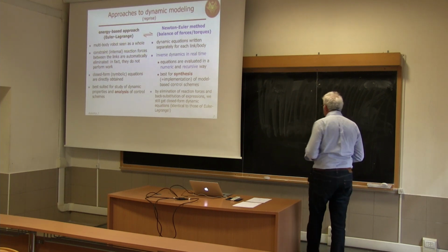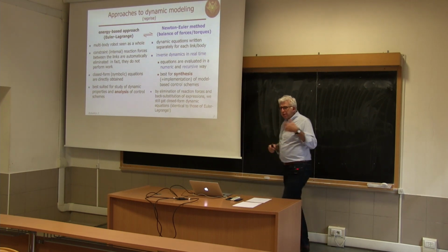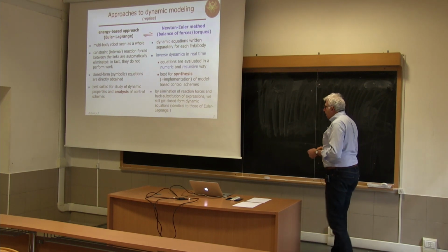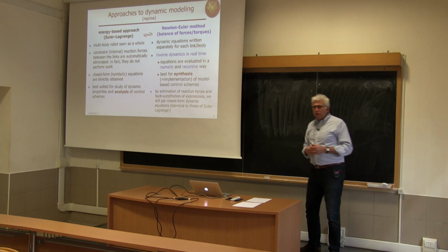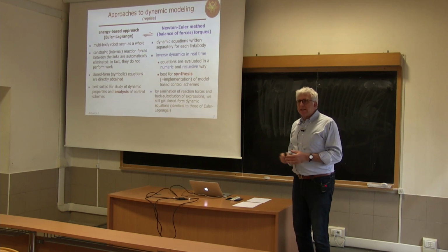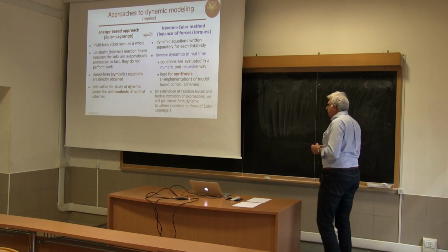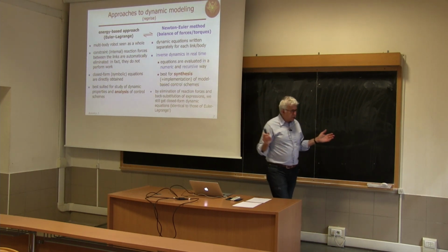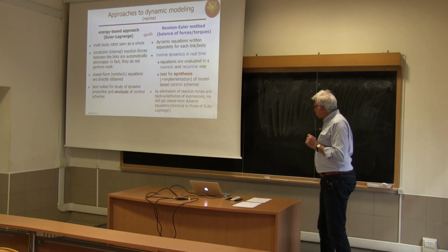So we plug in those numbers for any instant of time, so q at time t, q dot at time t, q double dot at time t. We make the recursion from the kinematical point of view. We compute numbers in terms of omega, omega dot, and whatever kinematic quantities we need. We plug those into the balance of forces and torques equation, and we evaluate this again numerically. So at the end, we have a numerical value of the torque needed to do the motion. So we never create long symbolic terms to be evaluated, although the two methods are, in fact, equivalent.